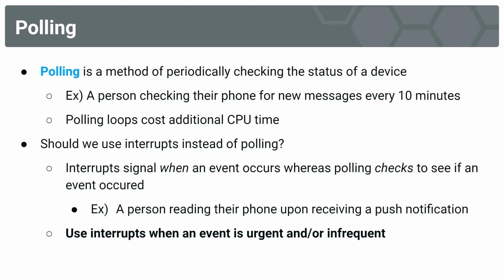But effectively, through this main loop, you are polling, and you are probably checking more times than not when an event hasn't occurred. So it's wasted CPU time. So instead, we could use interrupts for push-button switches.